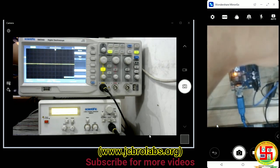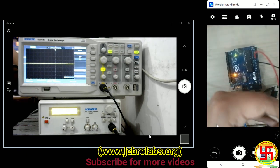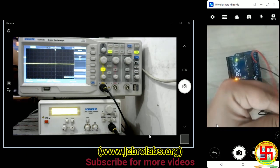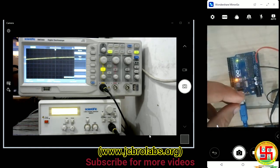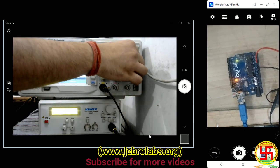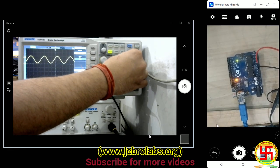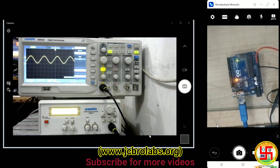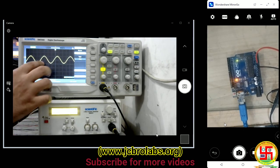Okay, so here it is. It was already there. So both the pins should come together now. Function generator is passing the data to Arduino, and the DSO is also taking samples of the function generator. So this is the waveform being generated by the function generator. 277 hertz. And if you look carefully, it is above 0, which I mentioned: the data waveform generated from the function generator should be above 0.